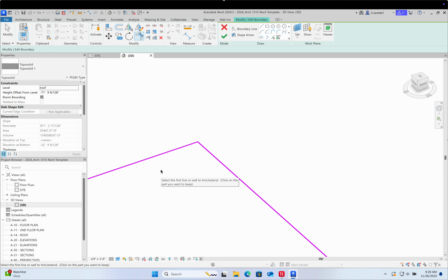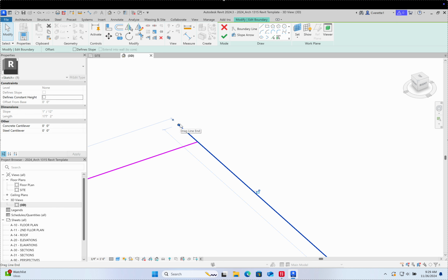Now again, kind of like trim, kind of like extend. To be fair, it's both. So for instance, what if this line is too large? I can do TR again. And again, the ones that I click on are the ones that it's going to keep. Watch that again. So I'm going to undo. TR is the command. There's no enter button, there's no escape.